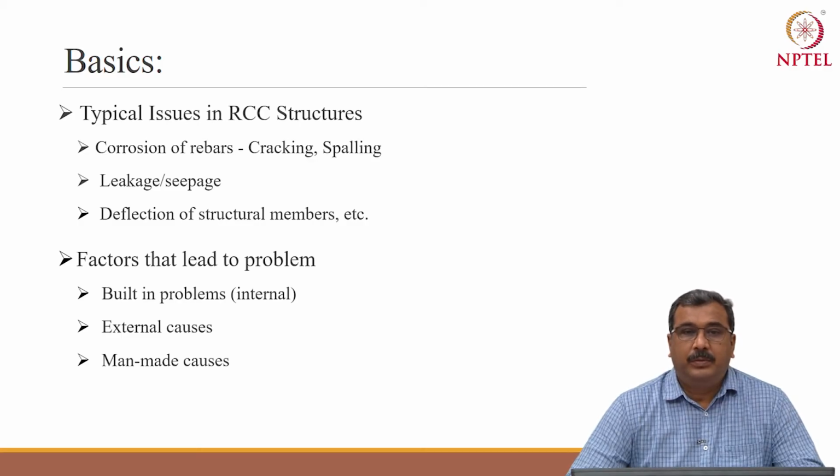Change in use. If a building has been designed for residential purpose and because of one or other reason, if the use is changed to a commercial or a hospital, then your loading changes and your building strength requirement changes and you need strengthening.